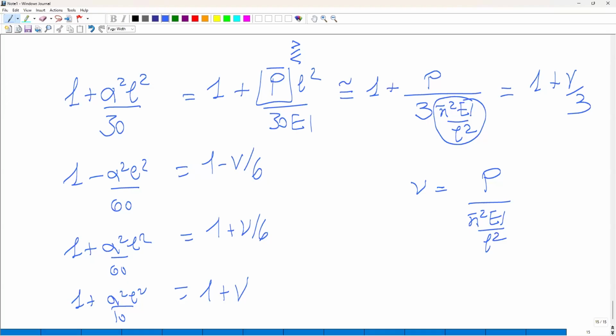Generally, when you do this, for example, if it's an apartment building, you may not even have built the interior walls. So you have to apply a load equal to the interior walls, the floors and so on, plus the live load. Because for that load level, the structure is surely safe, it's the service load.